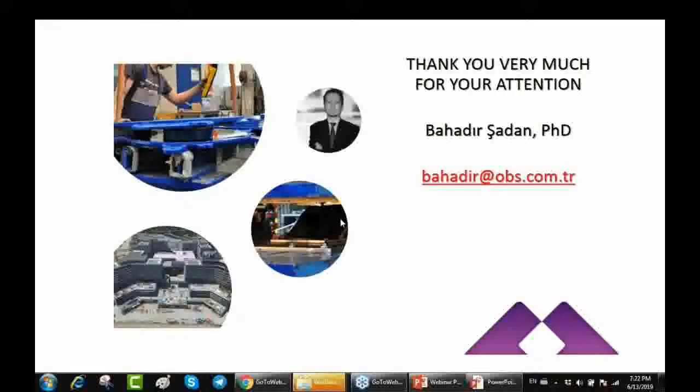Yadin asked a question. Is there any issue with stability due to overturning for base isolated buildings? Yes, you should check this, Yadin. Overturning is one of the biggest concerns for us. Therefore, we are not in favor of applying isolators to high-rise buildings due to the overturning forces. So you need to check your isolation system and your building for overturning forces. It's important. Therefore, we want buildings with low slenderness ratio on large areas, large buildings with low height.